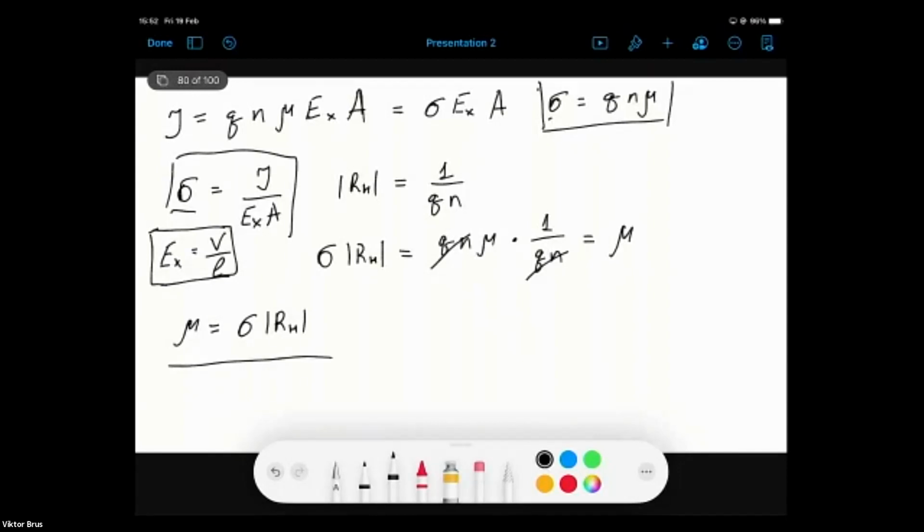So that means that with this second equation, by combining Hall voltage measurement and current voltage characteristic, we can get the unknown parameter, which is mobility of charge carriers. So eventually, we get independently determined concentration of charge carriers and mobility of these charge carriers.